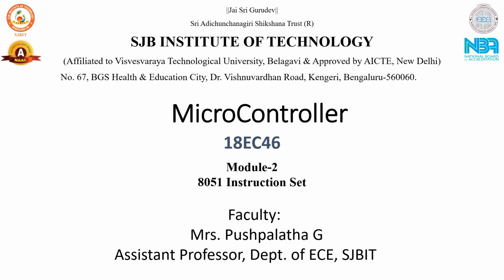microcontroller. When we talk about the microcontroller, the central part of the microcontroller is the computation unit, that we call the arithmetic logic unit, ALU. The ALU is responsible for basic mathematical computations such as addition, subtraction, multiplication, and division. And basically the ability of this 8051 is to perform arithmetic operations on 8-bit numbers. So we are going to discuss the 8-bit number operations using the 8051 instruction set.